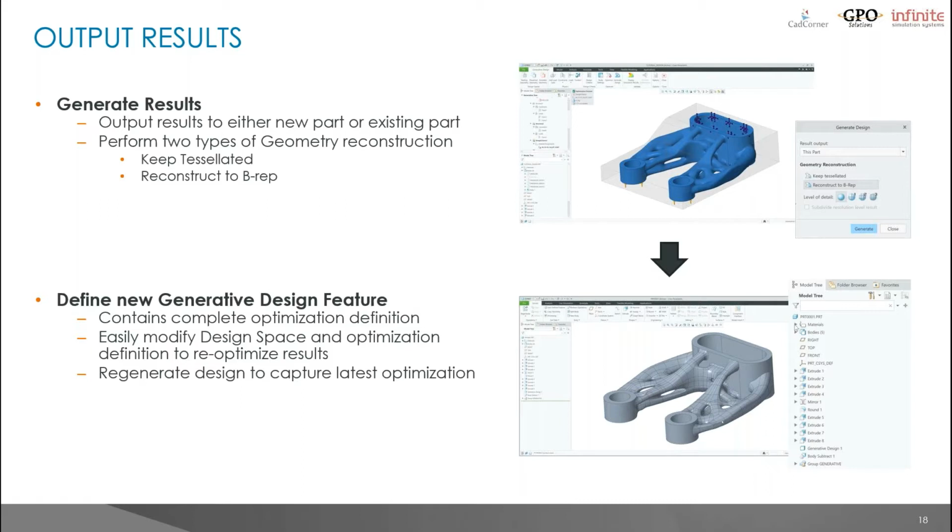The last bit you see in the model tree will be the actual reconstruction. This is nicely grouped in your model tree and is also assigned into a multi-body, so it's easy to perform additional multi-body operations or Boolean operations once you've completed your optimization.